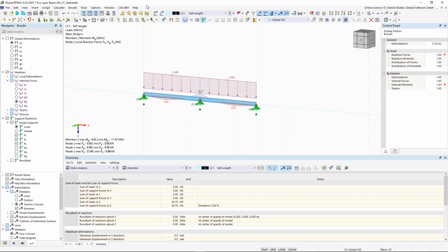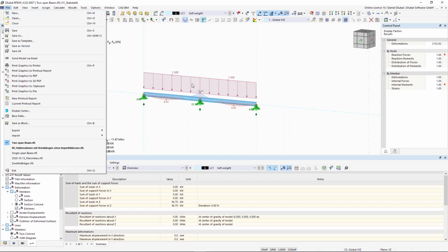What we can offer too is that you can create templates. You can save here, for example, this continuous beam as a template with those predefined load combinations. When you refer to this template, the defined load combinations will also appear. So just go here to File, Save as Template, and when you open this template, it opens the project with these definitions you made. That's a good point.